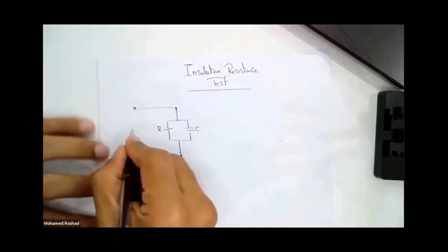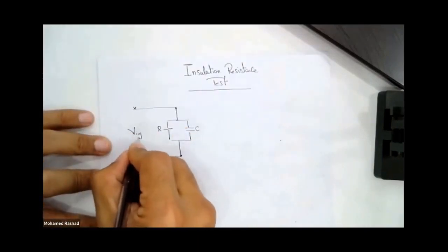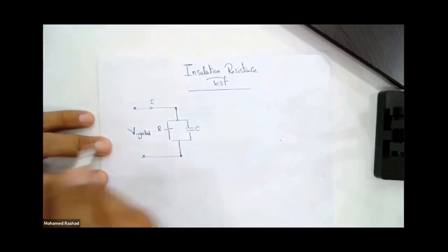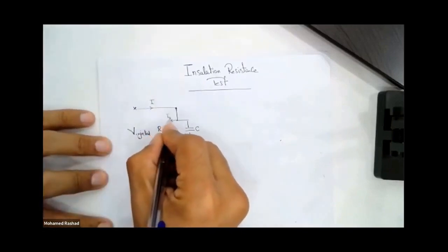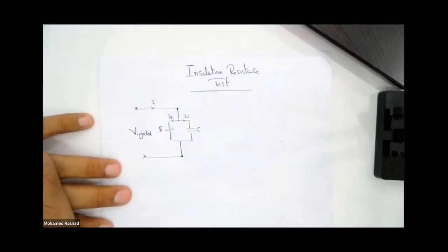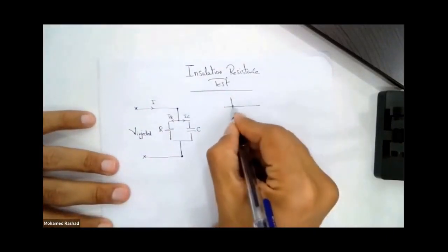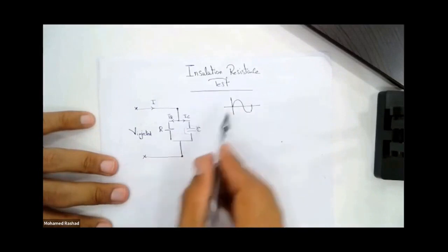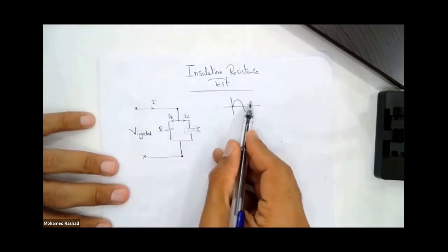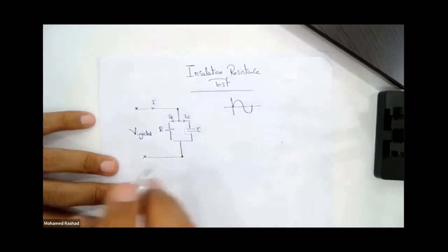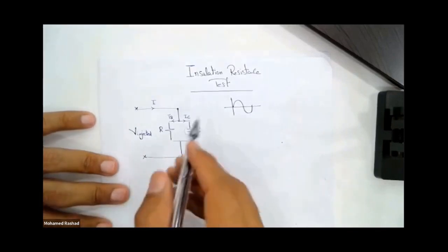Okay. Now, engineer, when you apply this injection voltage to your insulation, the whole idea is that this insulation draws current. This voltage, but the current is divided into two currents. One will flow through the resistance of the insulation, and the other will flow through the capacitance of the insulation. Exactly. Very good. So initially, engineer, if you inject AC voltage, this capacitor will keep charging and discharging. It charges in half a cycle and discharges in the other half cycle, and so on.